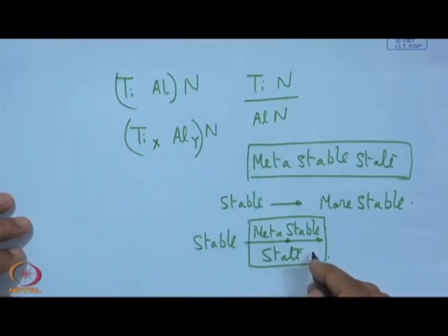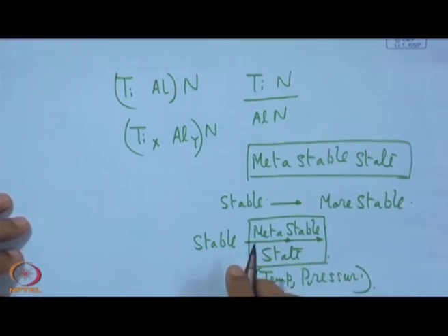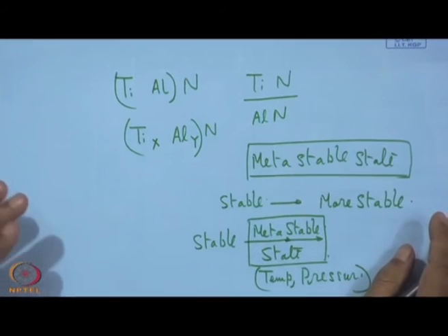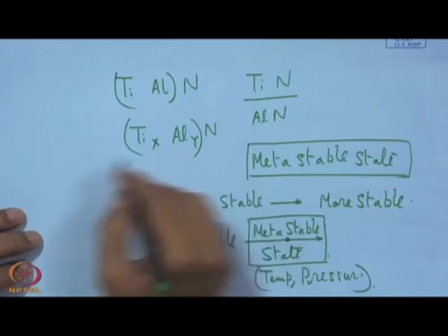So, this depends upon the particular coating condition, but in fact, it is the temperature and pressure. With that, it is possible to have a metastable state, and that is quite stable in that further movement to a more stable state does not occur. It is exactly that principle that is used. That means, just by having the sputtering condition, it is possible to have this kind of combination.